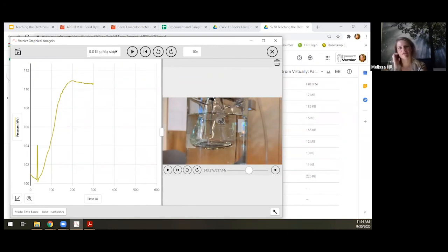Oh, a question came in about nickel sulfate not being safe to use. Not that it's not safe to use. I said there's a lot of reasons you might not want to use it, predominantly because you have to get rid of metal waste. Nickel cannot be put down the drain. So it costs a little bit more money to get all that and dispose of it safely. So that's one reason you might not want to use it. I believe you definitely look up the SDS sheet on it before you use it. There are some other implications of using nickel sulfate, but that's the biggest reason most people are getting away from it.